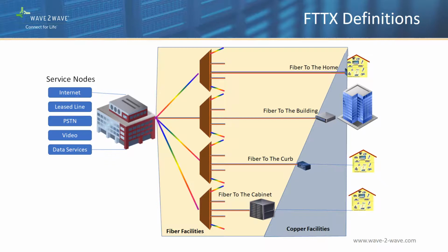There are also other common subsets of FTTH, such as FTTN, or fiber to the node, or fiber to the neighborhood, FTTP, fiber to the premises, FTTB, fiber to the basement, etc. The FTTH network will have large fiber counts for accessing as many homes as possible. For instance, reaching a neighborhood of 3,200 homes, an outside plant cable would minimally require 100 fibers, 1 per 32 homes, based on full utilization of the 1x32 optical splitters used in the outside plant distribution.